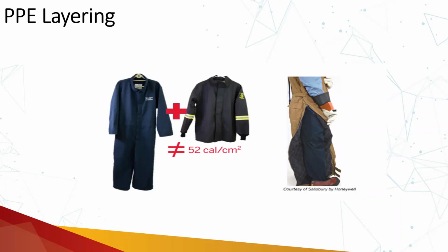Okay, moving towards the PPE layering concept. What is the PPE layering concept? Wearing a 40 calories per centimeter square suit is one option. But we know that those 40 calories per centimeter square suits are very heavy, very difficult to carry as well, and you cannot perform the jobs for a longer duration of time. So there is another concept of layering.